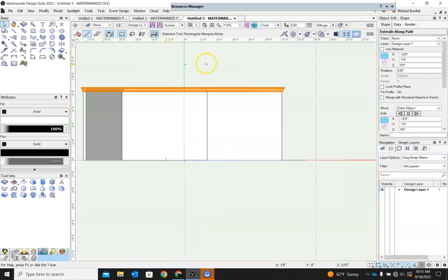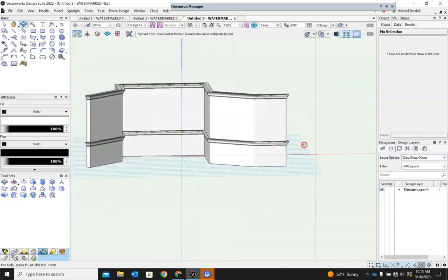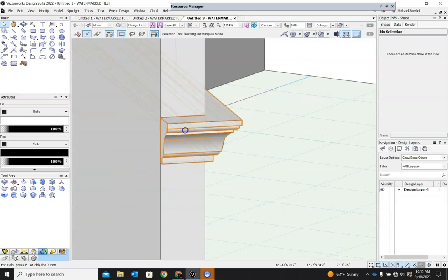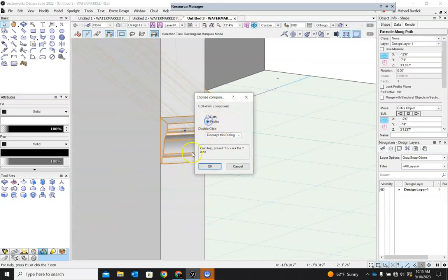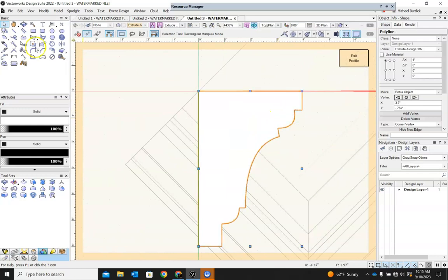the front view, and we'll just pull it down to, I don't know, wherever our chair rail would be. Let's say 30, 32, 36 inches off the ground. So now we've got a chair rail too, except that is a huge molding for a chair rail. So let me double click and I will change the profile on this. Here's our profile. I'm going to draw something completely new.